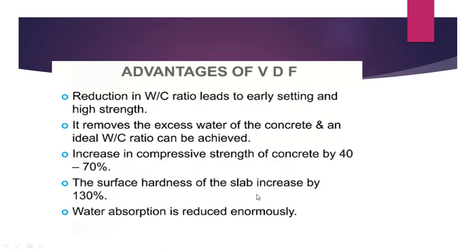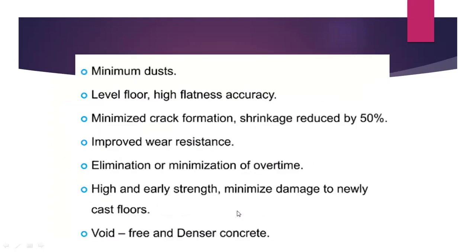The surface hardness is also increased by 130%, and water absorption is reduced enormously. There are some additional advantages also. It gives you minimum dust, level floor accuracy, minimum crack formation, improved wear resistance, elimination and minimization of overtime, and a high and early strength floor. We also get a voidless and denser concrete.